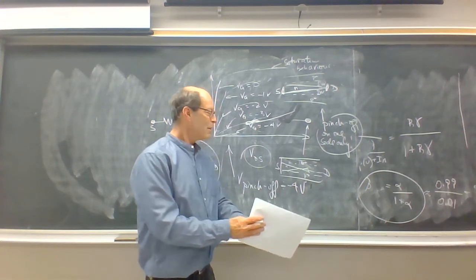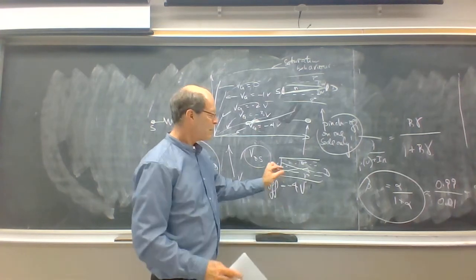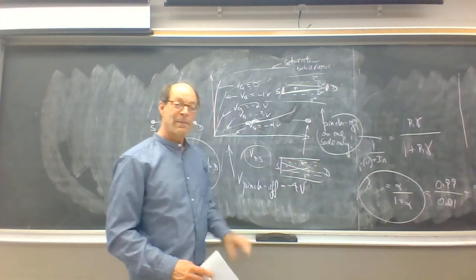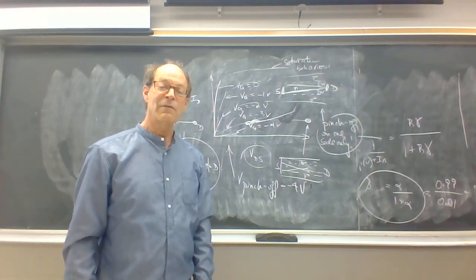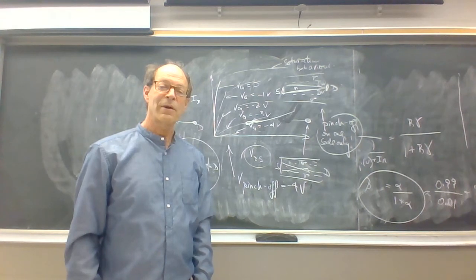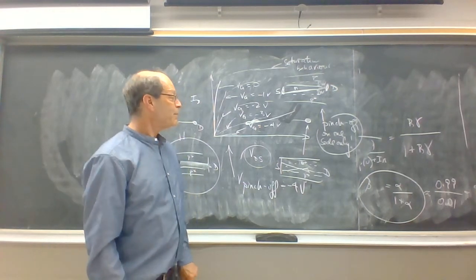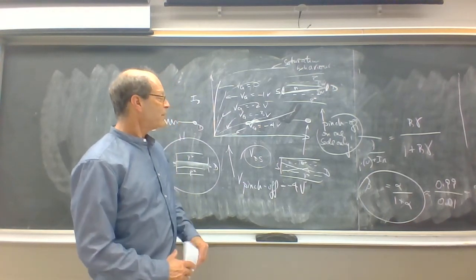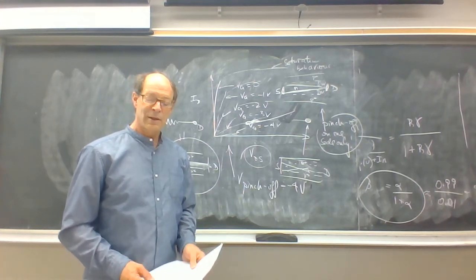You can't cut the current off, and you'll find that there's a very skinny flow along a virtually infinitely thin channel, but you don't lose the current flow. The current continues to flow through the device. So the characteristic curves of a junction field effect transistor look like this.